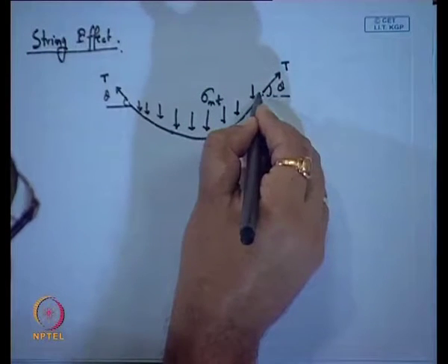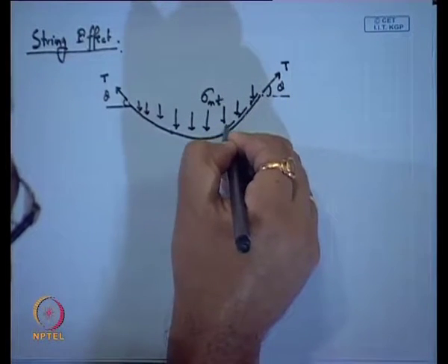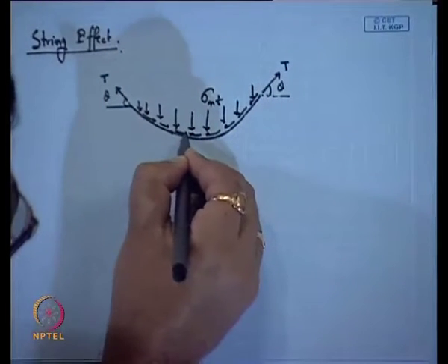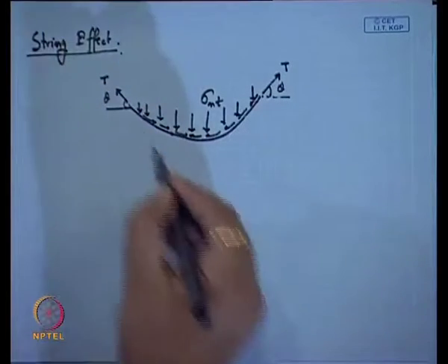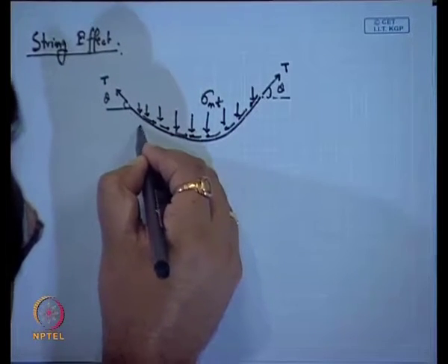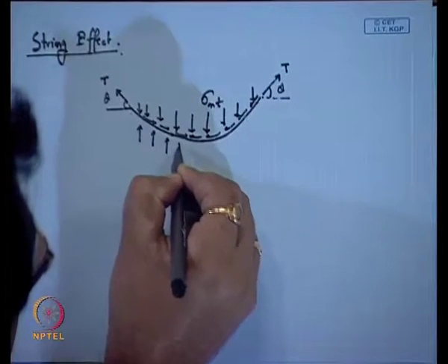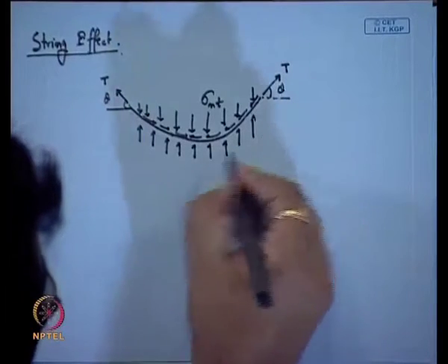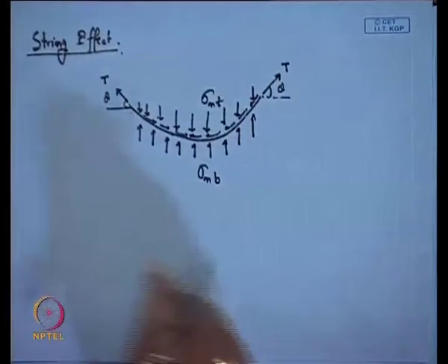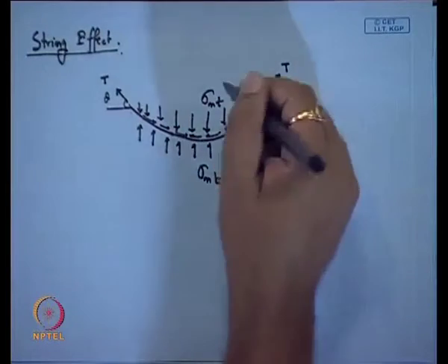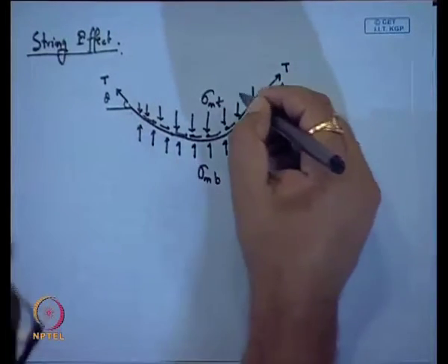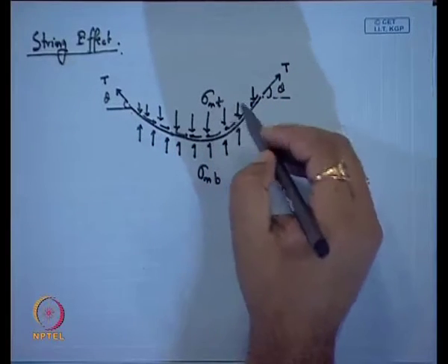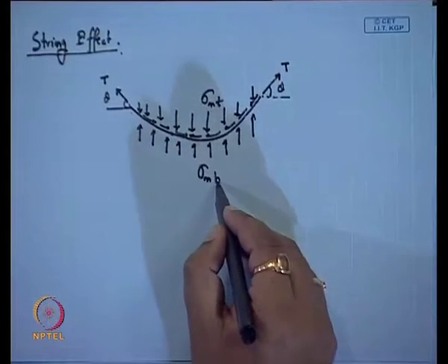Because of these things, this shear force will act here also, and the reaction force here will act in the bottom direction. So, this is sigma n b. These are the two vertical stresses that will act. So, this is sigma n t at the top of the reinforcement and sigma n b at the bottom of the reinforcement.